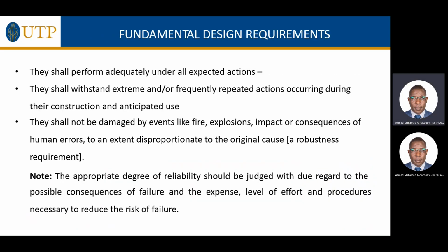The fundamental design requirement for offshore platforms is that they should perform adequately under all expected actions, considering the environmental load and the accidental load. In addition to that, if these complex platforms are subjected to fire, for example, or to explosions or impact load, then these platforms are not supposed to fail.